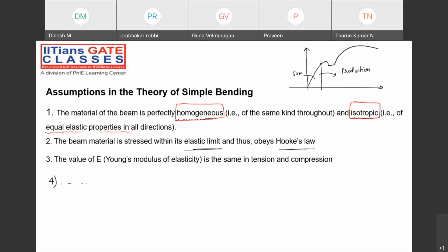So just try to think and tell me about homogeneous material. We will try to learn homogeneous material. Homogeneous material is saying that in any body, non-rigid body or deformable body, when the elastic properties are the same at all the points in a given direction, then I would say that material is a homogeneous material. That means if I assume my x direction, y direction, z direction, this is a point P1. Elastic properties are the same at all the points at a given direction.